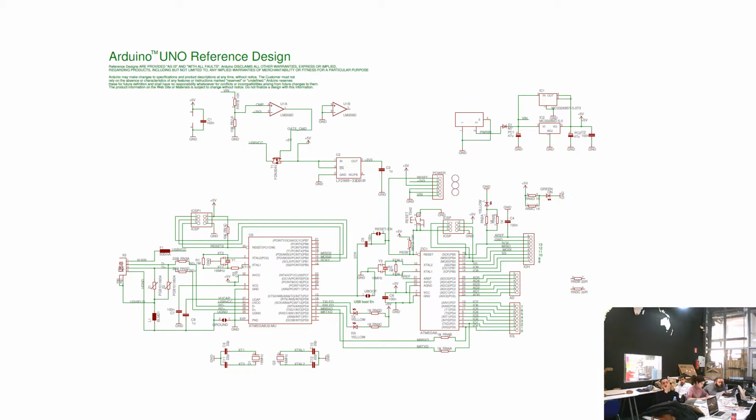The concept you need to know is to forget about all that and just think that for the chip you'll be working on, you'll always need a programmer to program them, and that you'll build your own programmer. That's the only thing. And you'll build your own programmer using the same tools. So it's kind of a chicken and egg problem. You will always need one of them to flash your programmer. So your programmer will look like this at the beginning. You'll need to put code inside through here. And so the first one will need to use that, and then all the rest will be able to use your colleague's programmer.